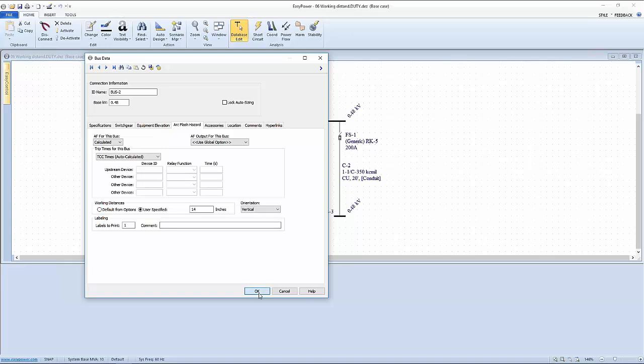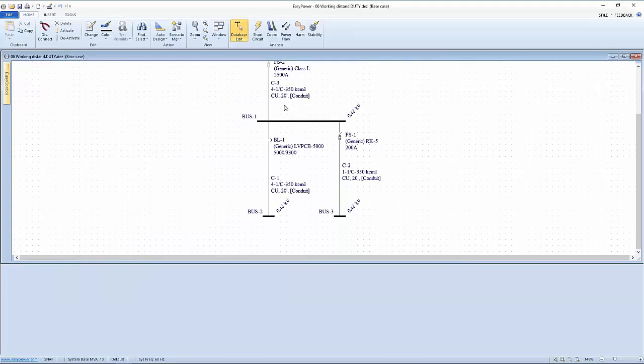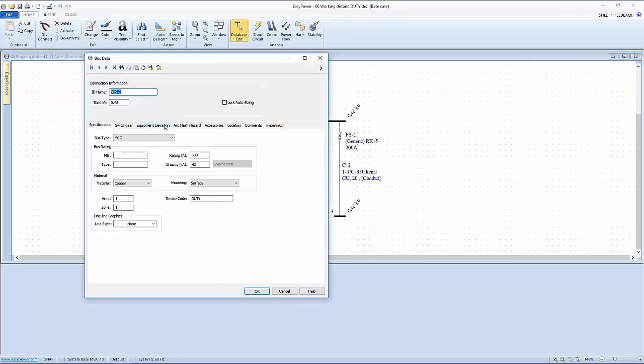While I'm here, you'll notice that when I was back in short circuit focus, I started off with incident energy and equipment duty. It turns out I had a question from a customer that says, what should we do to the label if we know that we have a duty violation on a certain bus? We want to warn the operators of that condition, because it's going to take us some time to fix them, to change the breakers.